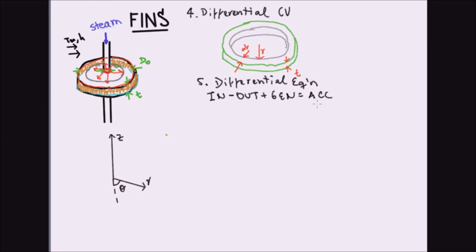We can definitely cross this out, because we said originally that one of our assumptions was that we didn't have any time dependence. The temperature doesn't change with respect to time. There's steady state, so this is equal to 0. What about generation? Does the fin generate? Does it sink any heat?